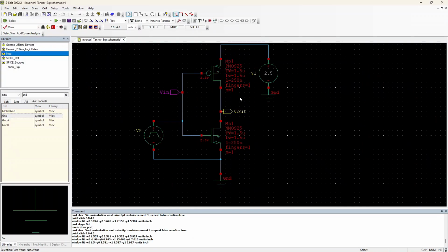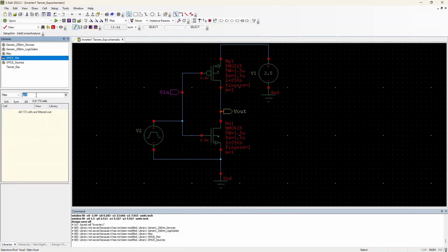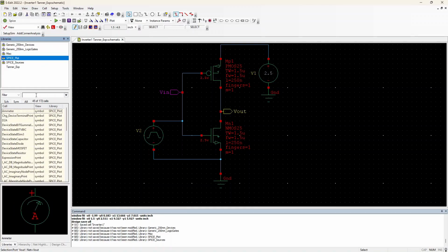Now in LTSpice, what used to happen is that you will just simulate it and then you will put the cursor at some points and it will plot those voltages. Here you have to mention those probes in advance. So here in the print plot, search for print. You want to print voltage, so the last one is voltage print.